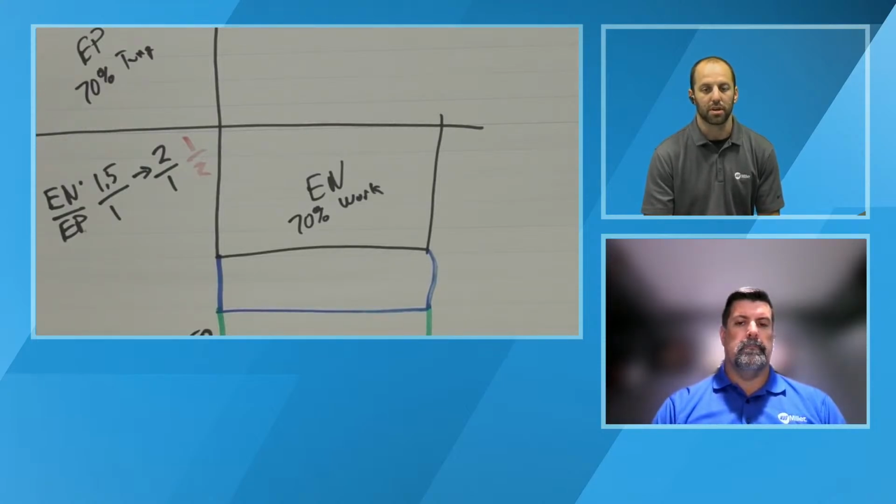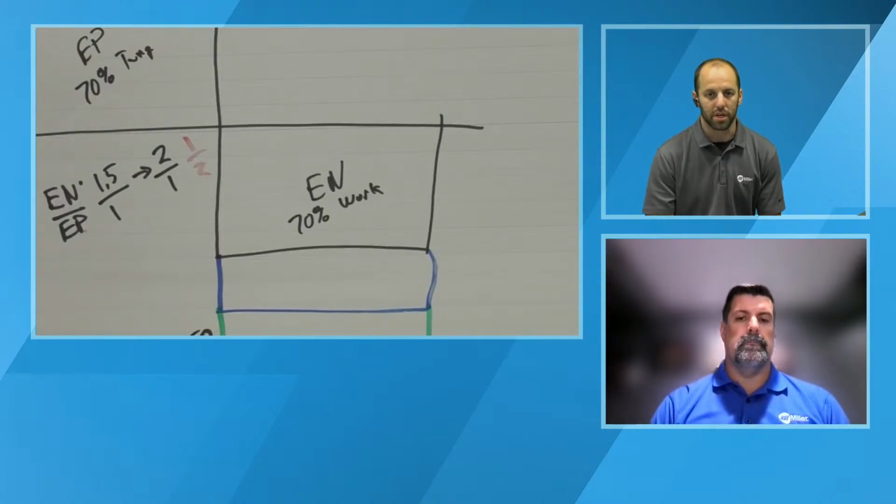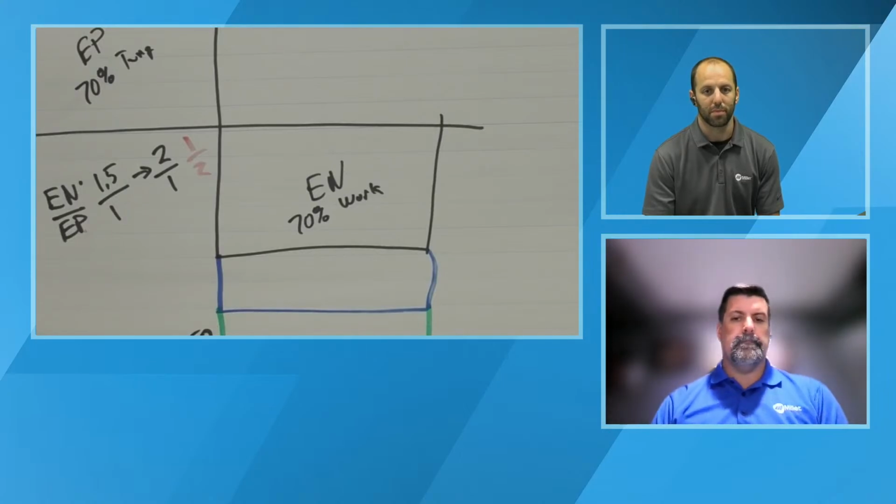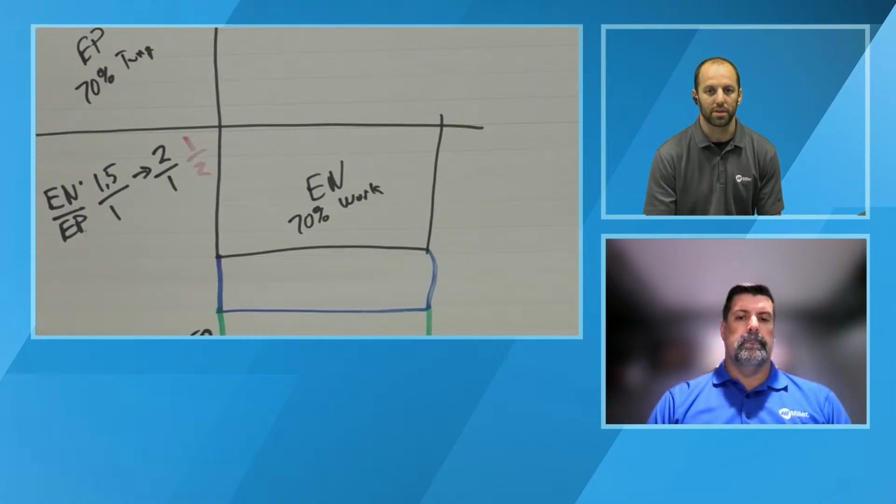My personal preference is, if you're 1/4 inch or under, truncate it to a third or maybe even a half the electrode diameter. The corners will naturally round off on their own, but you're not going to get a true one diameter ball on the end of it.